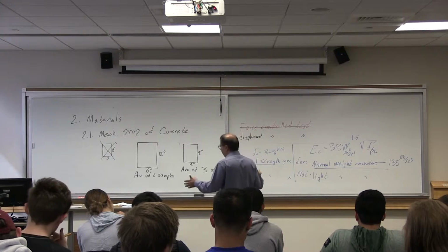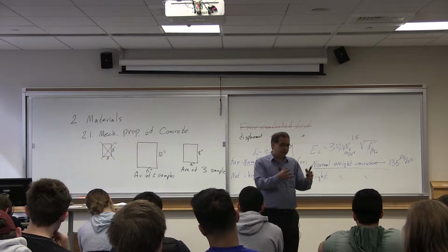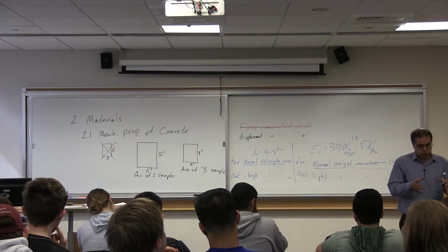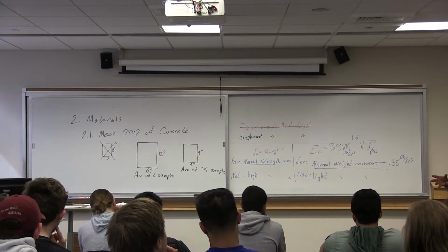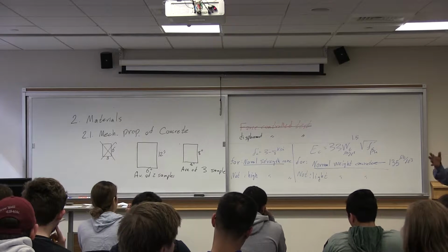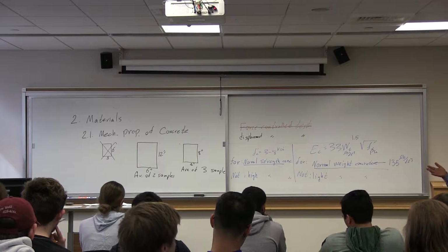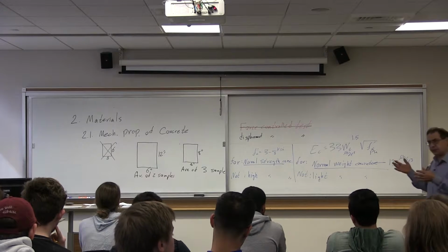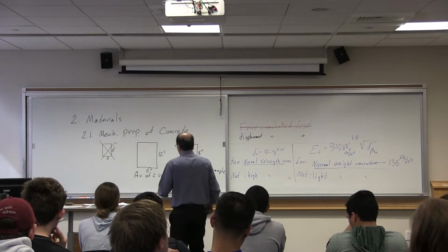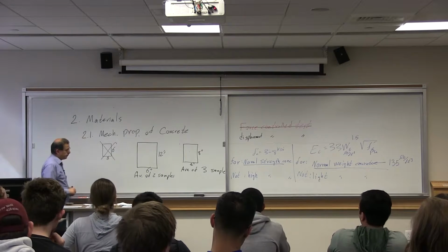Let's say someone from the US wants to study a building in Europe, and they have samples in terms of cubic samples. You cannot just directly say, okay, I assume cylinder is the same. People have developed over time relationships for how to convert them. There are different curves, different ways of converting them, but that's not really our issue. We just look at those cylinders.